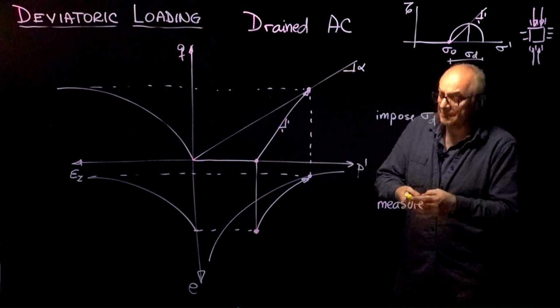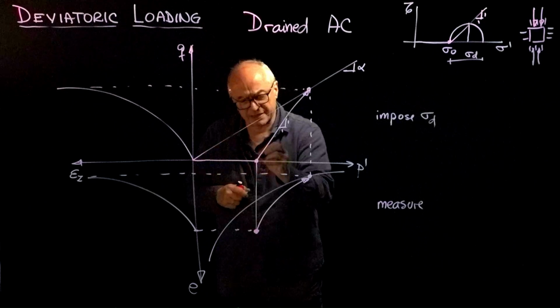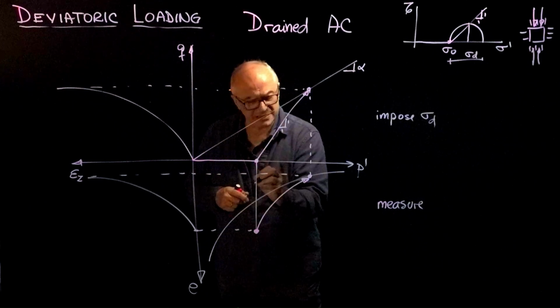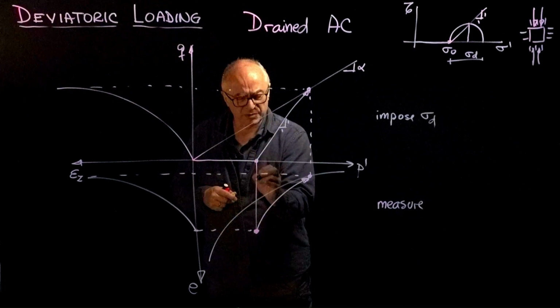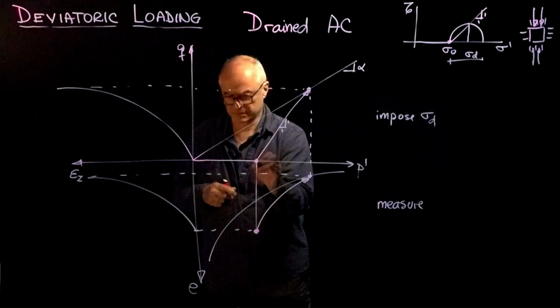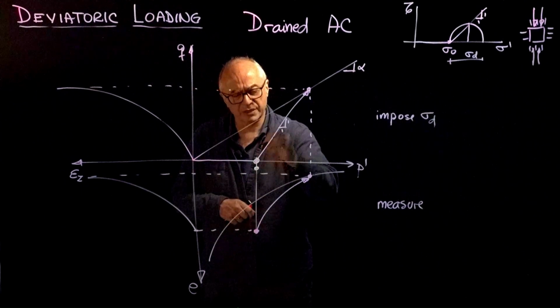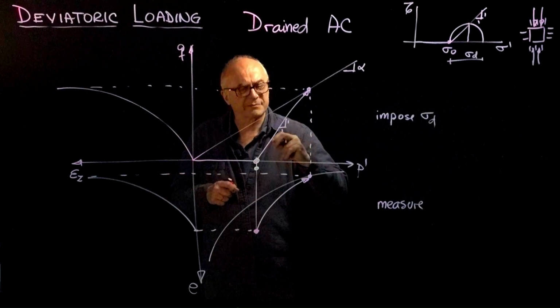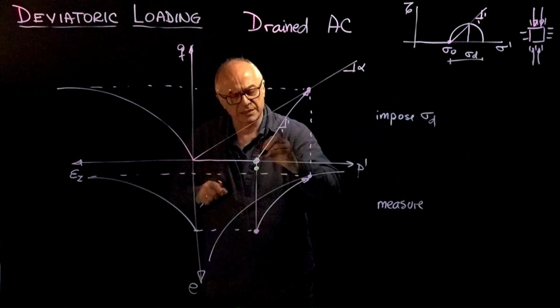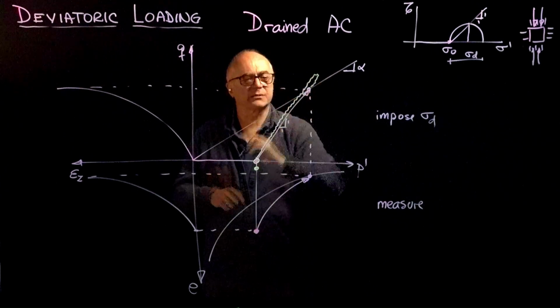So how does this manifest in this case? We confine the specimen, but we have to recognize that that specimen is going to be under dilative conditions. So it's going to be somewhere here. This is the initial point, and that is the initial point. The soil will, in order to highlight the colors, I'm going to wiggle the lines, but unfortunately colors do not capture the whole detail, so please follow it carefully. So it will go up, overshoots, and then it comes down.